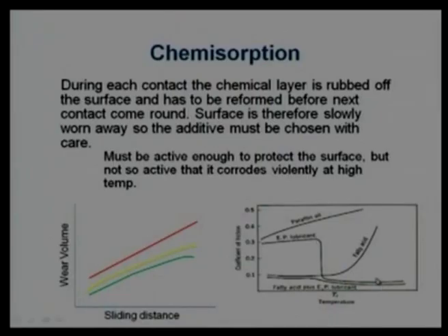That is why I mentioned in my last slide also, whenever we make a lubricant, we generally add chemicals related to physical adsorption and chemicals related to chemisorption, and EP additive is another form of chemisorption. We say that it happens under high temperature and extreme pressure. If pressure is very high, temperature will also increase there. So they are related, or chemisorption phenomena can be said to be extreme pressure phenomena.